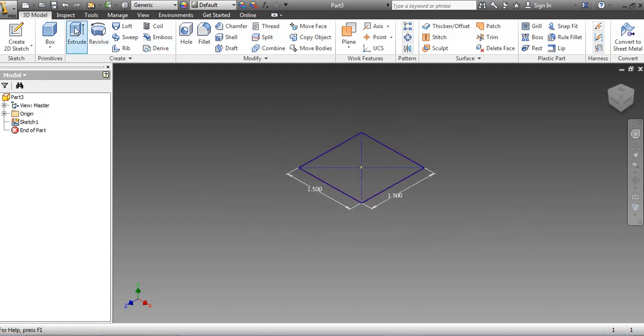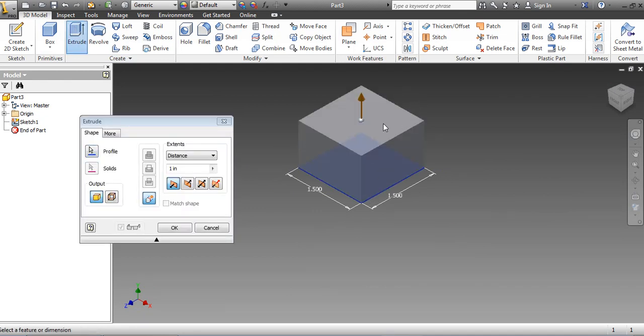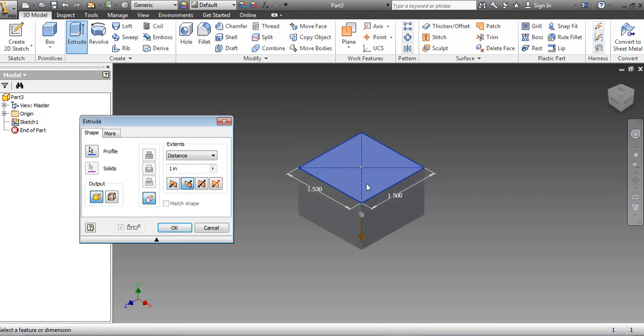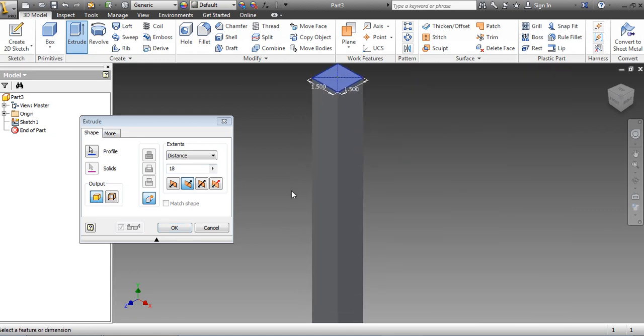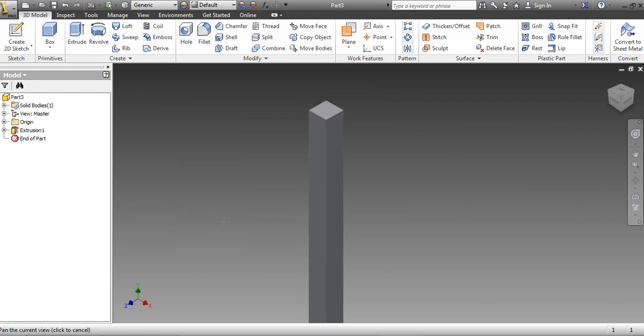The next thing I'm going to do is go to Extrude. Okay, so I hit Extrude, and it just automatically extrudes this one part because there's only one part. Now, here's where this is going to be a bit tricky. There's different things I can do in here, but for this particular tutorial, what I want to do is I'm going to reverse the direction, and you'll understand later on. So I'm going to reverse the direction down, so this is the plane I'm working on, and I'm going to go down direction, and I'm going to make this a total of, I don't know, let's say 18 inches. Okay, so it's going to be an end table. So we just do that, and I can zoom out and you can see where I'm at. So there's my leg now, and then I'm just going to hit finish. So that's all we're going to do in this part of the tutorial.